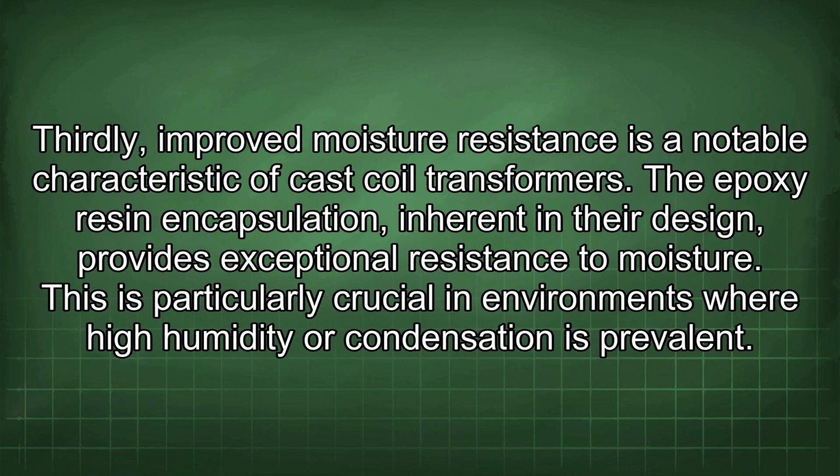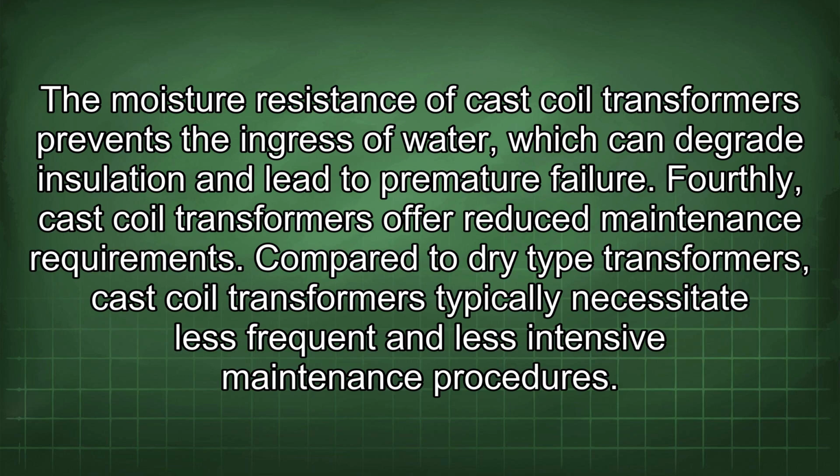Thirdly, improved moisture resistance is a notable characteristic of cast coil transformers. The epoxy resin encapsulation inherent in their design provides exceptional resistance to moisture. This is particularly crucial in environments where high humidity or condensation is prevalent. The moisture resistance of cast coil transformers prevents the ingress of water, which can degrade insulation and lead to premature failure. Fourthly, cast coil transformers offer reduced maintenance requirements.